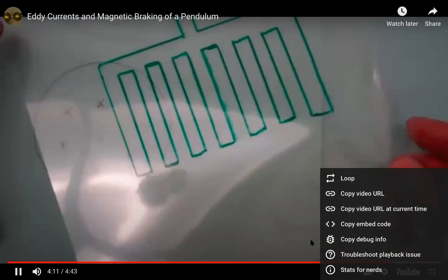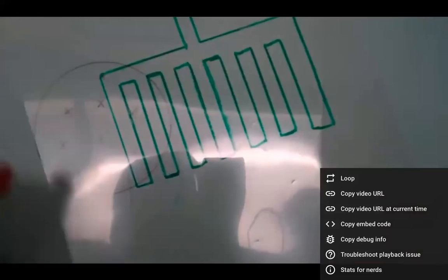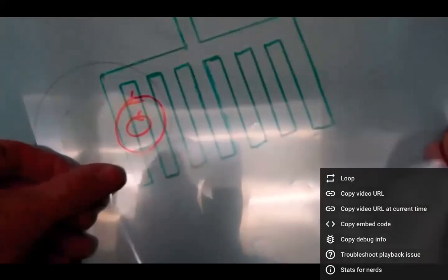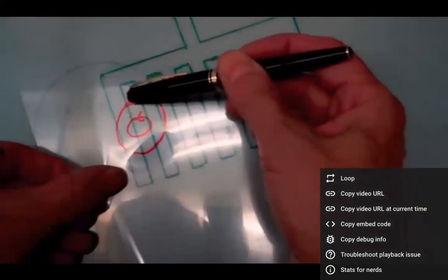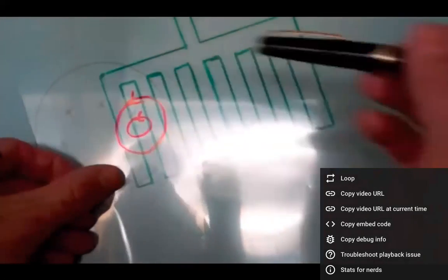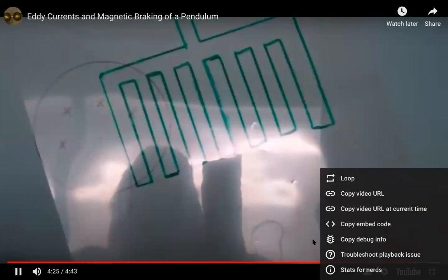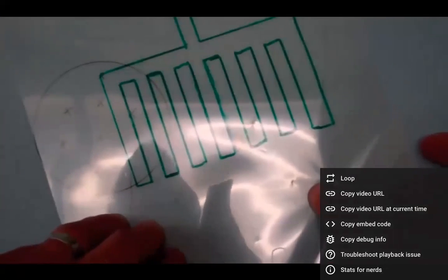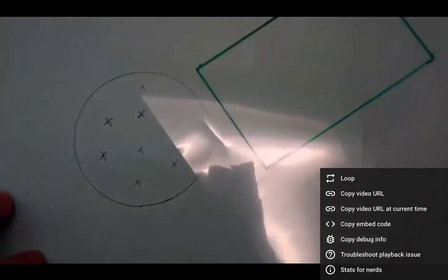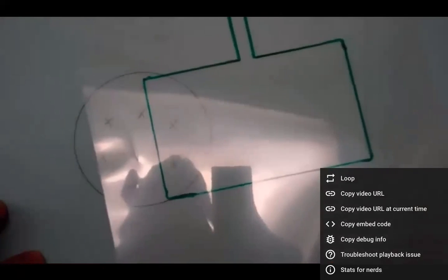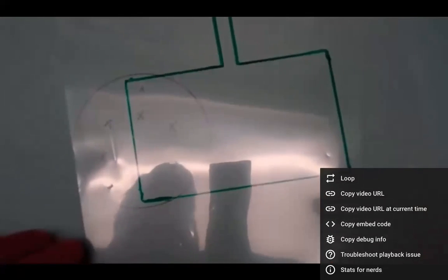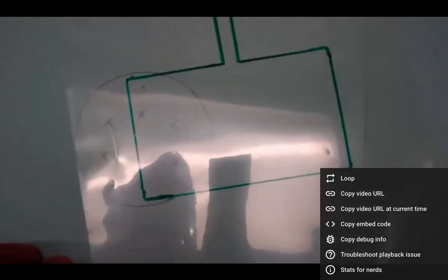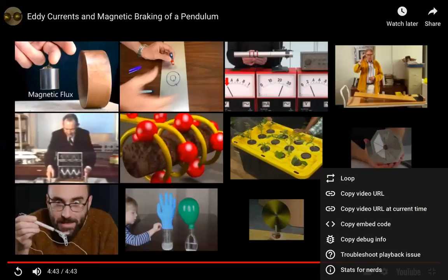Now, when the pendulum with the slots slides into the magnetic field area, these eddy currents cannot flow because you have discontinuities, the high resistance air gaps, so you're not going to get those eddy currents and the resulting same large opposing magnetic field. So the kinetic energy of this pendulum as it's sliding in is converted to heat in the aluminum due to the eddy currents.